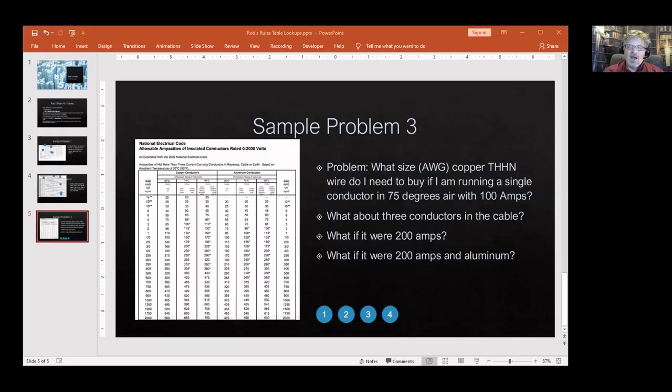If you buy too big a wire, well, it's not so big a risk, but you will be spending extra money because copper wire is expensive. And in this particular example, step 1, which is choosing the right table, is critical. Because if you look up these tables, here I am showing my booklet here, in your reference or your generic reference books, you're going to see a dozen different tables about wire sizing. So you have to make sure you're choosing the right table, right? And so let's begin this process here.